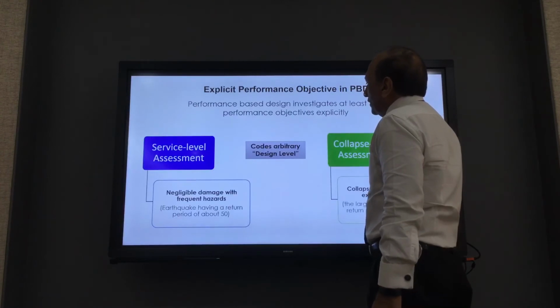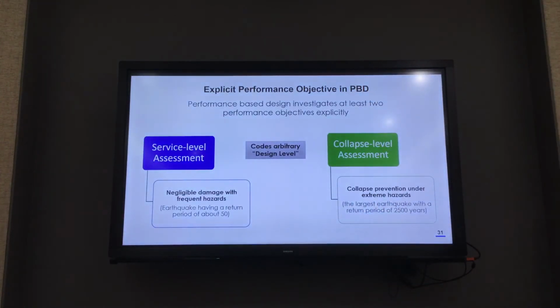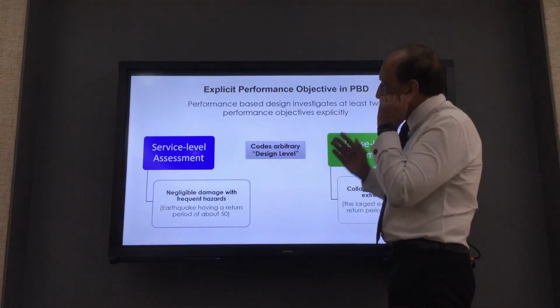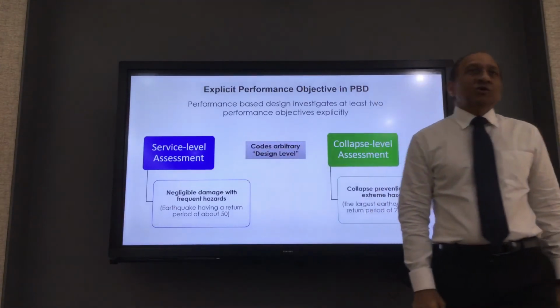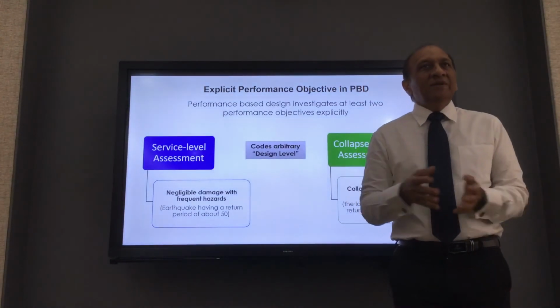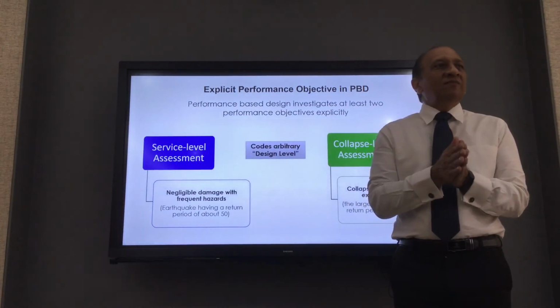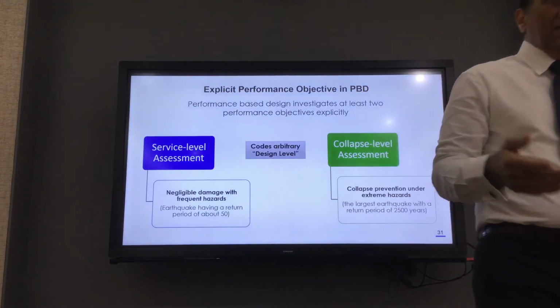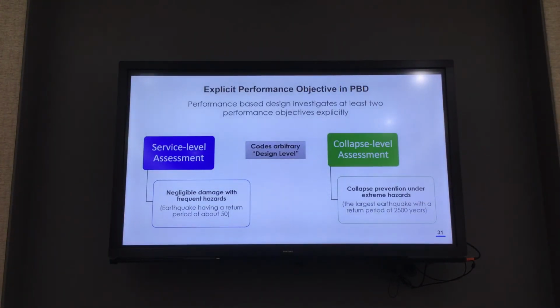So this is the overall system for performance-based design. Please watch this carefully. I think you have seen it before, but see it again. There are two real levels in a structure's life. One level is service level. Now I'm talking about earthquake for now, but it is applicable to others also. One is the service life, daily. That means a service level earthquake or service level wind or service level loading, live load today. This is service level. That means things that will happen routinely to the structure.